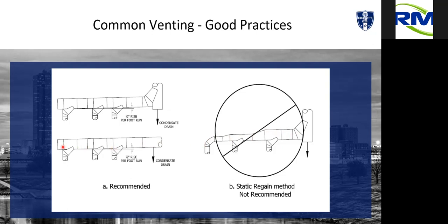Many times what will happen is they'll give us a common header past all of them except for the last one, and then they'll neck down to get that final appliance. I can make that work. It's just not as clean of an install for us for pressure readings, because we actually would prefer to be out of the airstream and actually just read pressure. So that's why we would prefer to have that nice common header all the way across and past that appliance.